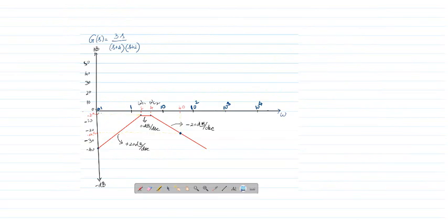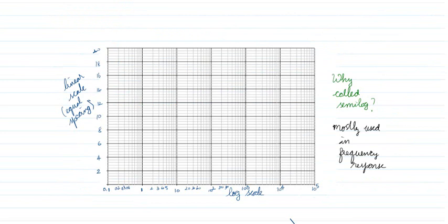Okay, this is the plot that we are going to see. This is the magnitude plot, right? Before going to the magnitude plot, we have to see that we will be plotting things in a Bode plot on a semilog sheet, right? If you look at the semilog sheet, we can see this y-axis is evenly spaced. The distance is equal, right? That's why I say it's linear scale, equal spacing.